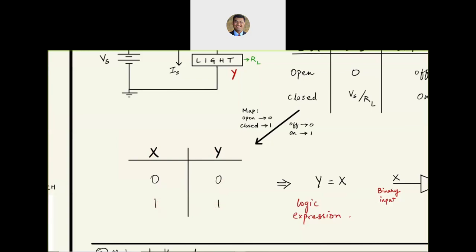So here we have the binary input, and over here we have the binary output, and it is binary because we have only two states, 0 and 1. And as you can see, the input is exactly the same as the output. So that's an identity function, and this table is called a truth table. A truth table includes or should include all the possible binary levels of each input. So in this case, you only have one input, so there will be two rows in this table.